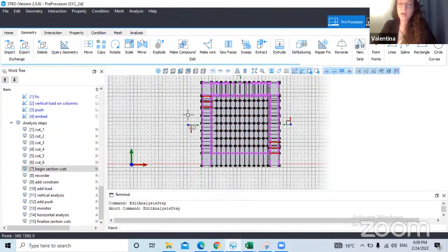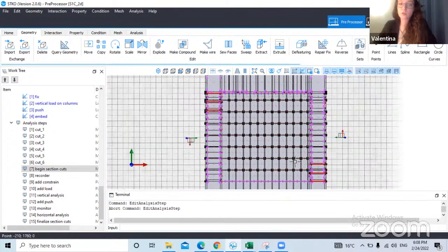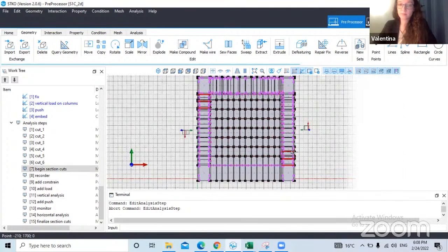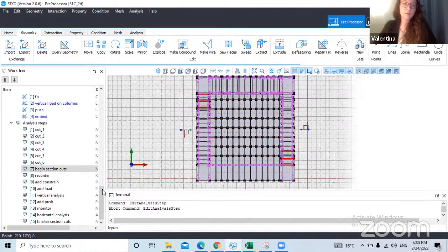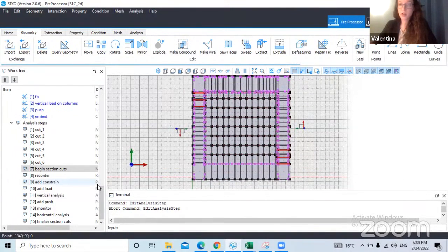In my case, I'm measuring shear in 6 different sections where I expect the maximum. So it's the left upper angle of the column, you can see it in red, and also 3 section cuts here. I can explain a little bit how we did it, for someone who is also interested in this.